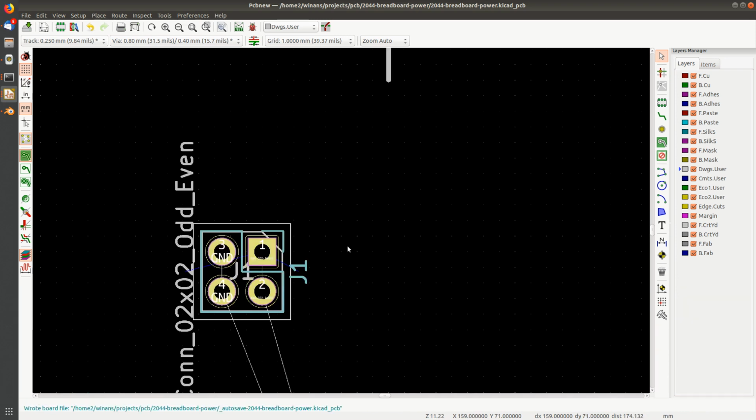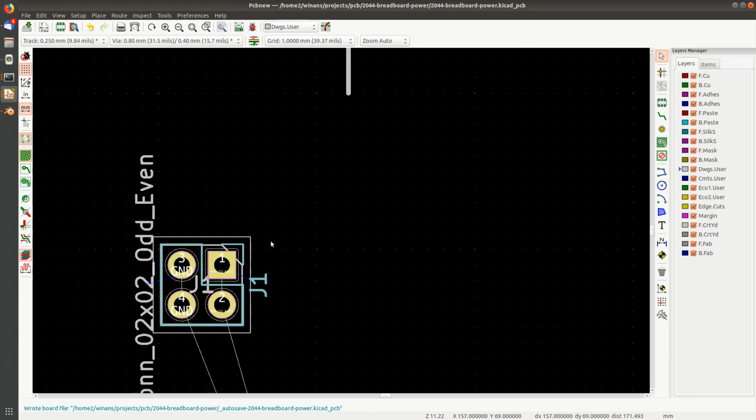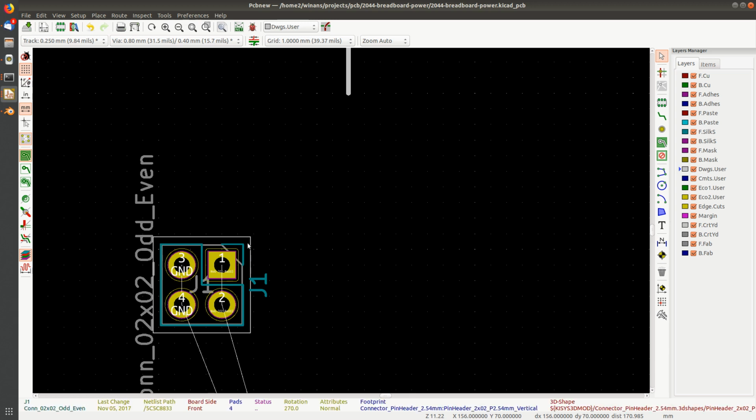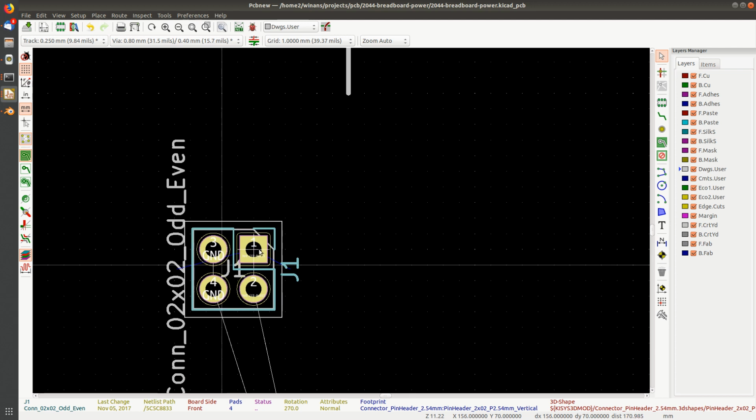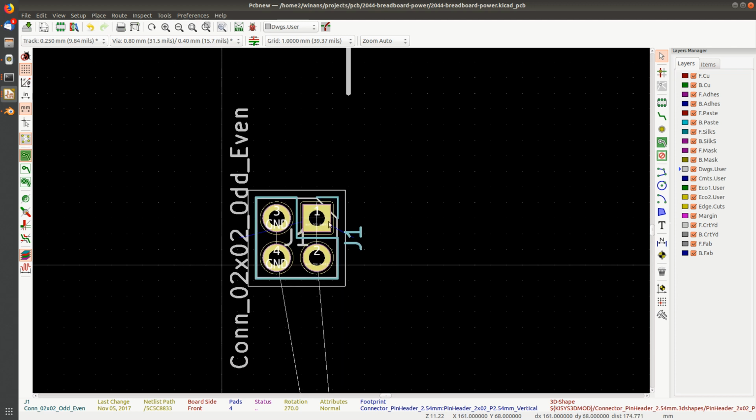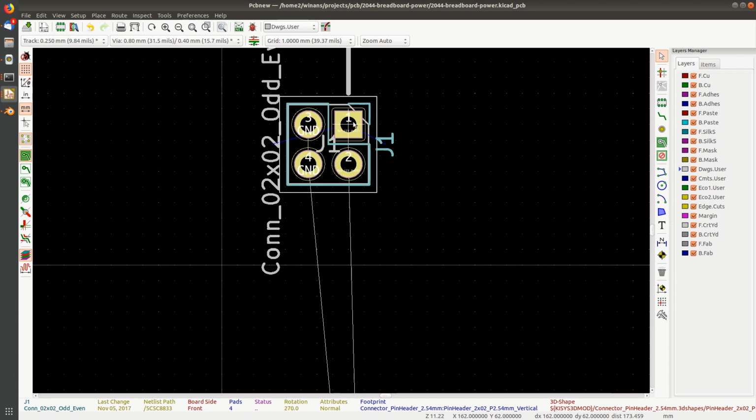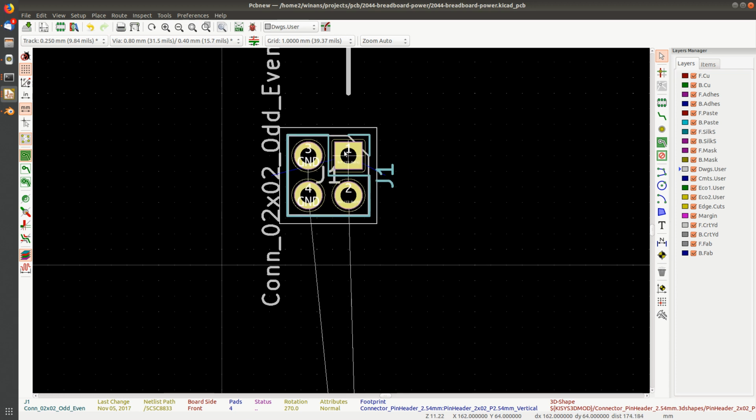I've used a number of different CAD packages, and some of them let you do things a little bit differently. So what I'm doing here is if I grab the part by clicking here and I select the whole thing and I hit M, you'll notice it wants to align my movement in reference to where I'm placing it on pin number 1. That's actually a feature of KiCad.